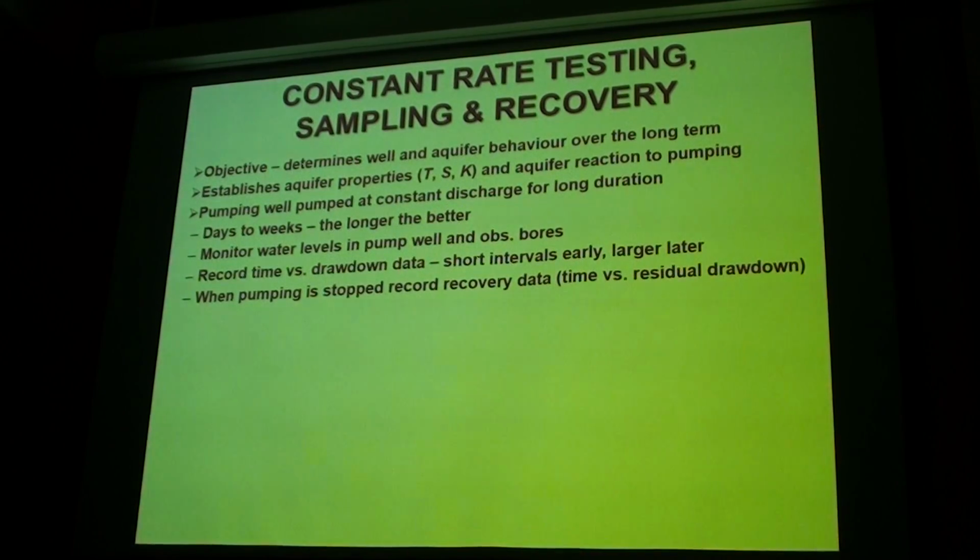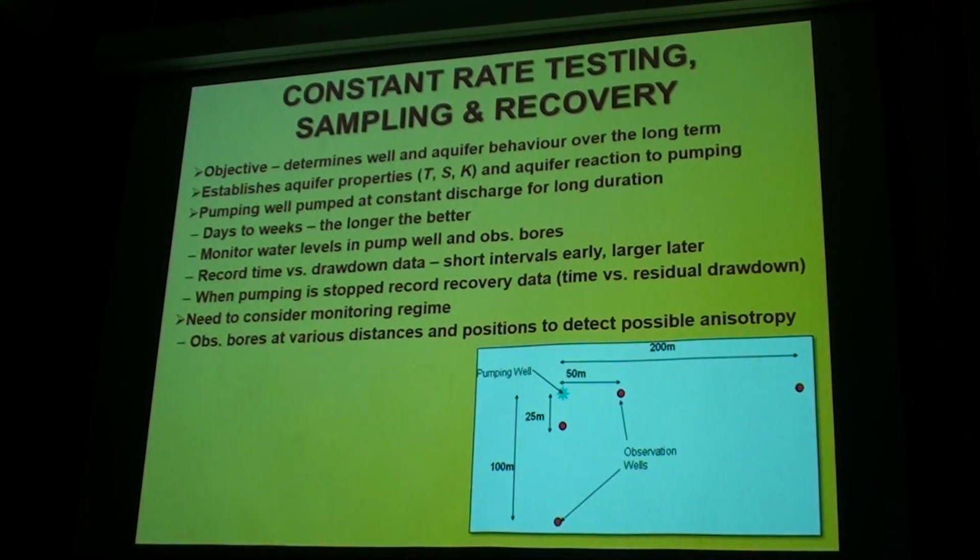Don't stop recording when you turn the pump off. Right? You record the opposite here. You record recovery. So water levels in the well recovering, water levels in the aquifer recovering as well. You need to consider how you're going to monitor your pumping test. Okay. It's very important that you don't just have, if possible, your pump well and one observation bore. You need several, and preferably at varying distances away and in different directions away from the pump wells.